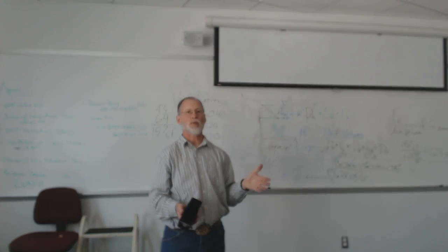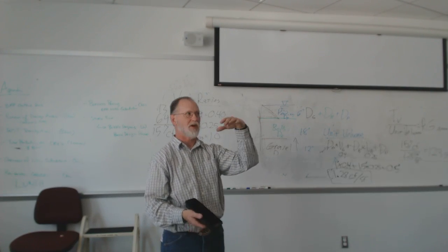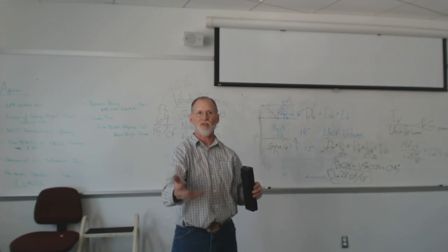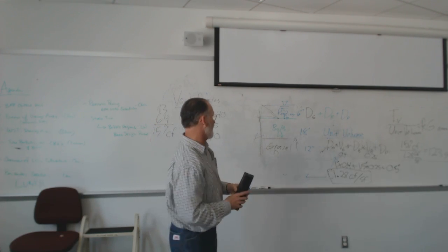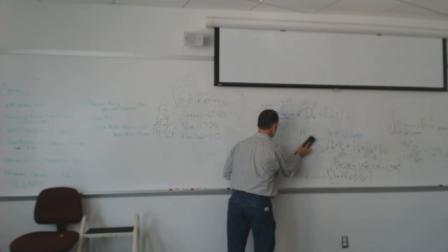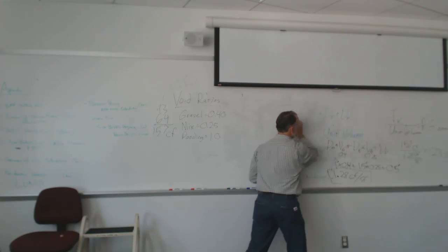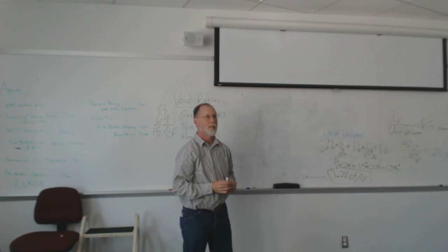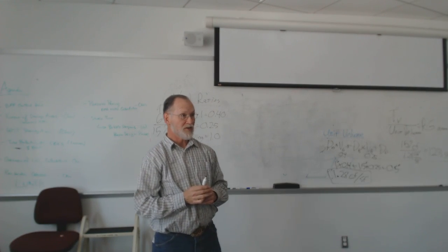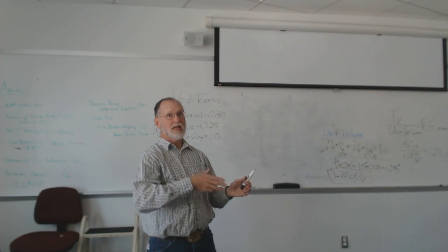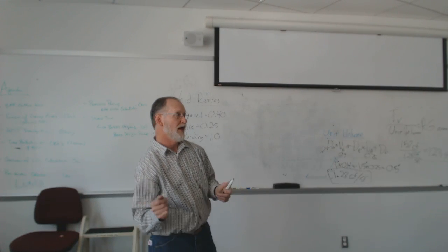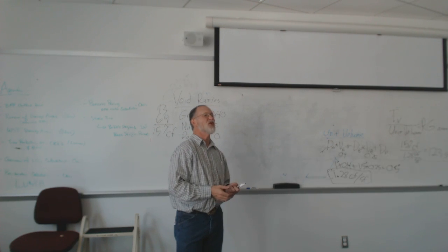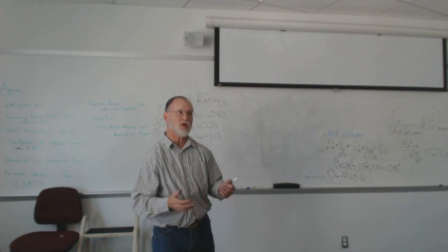So that's a difference. If you're doing a residential rain garden, you're not going to have 18 inches of design biomix in there typically. A lot of times they're digging out the soils they've got, amending them a little bit, and having some ponding depth. But this is for the fully designed regulatory bioretention area. And you said that was typically 18 inches minimum? Minimum, 18 to 24. In Virginia, if you're going to what's called a level 2, where you get more treatment credit, 36 inches of bioretention mix.